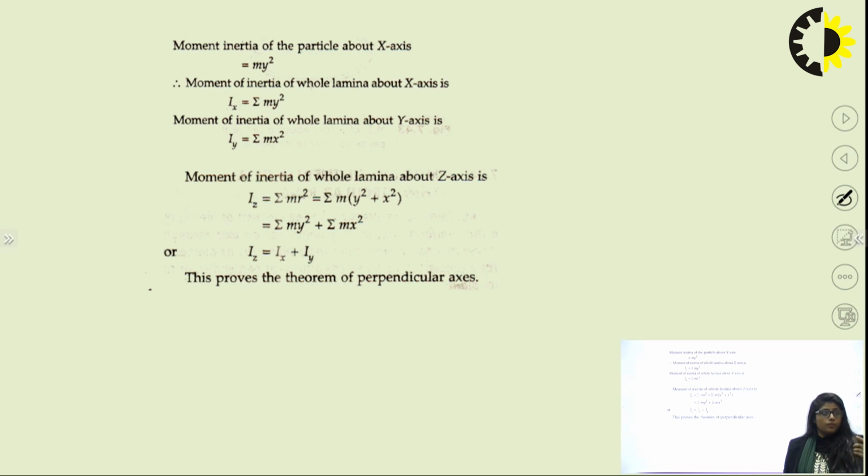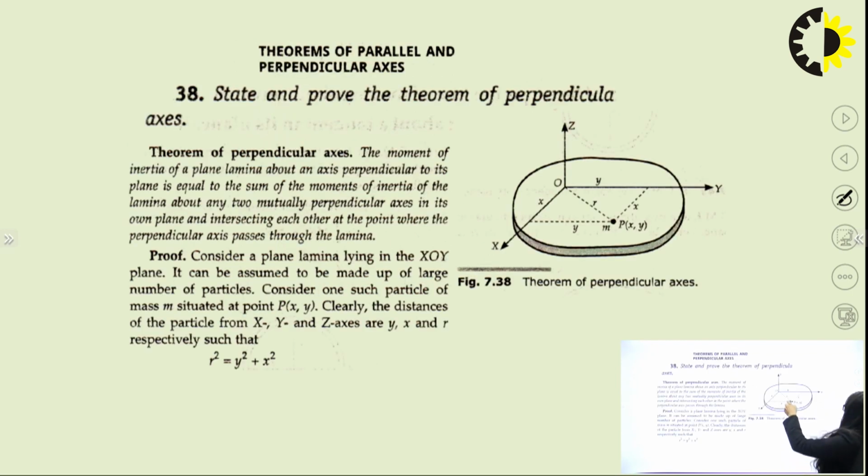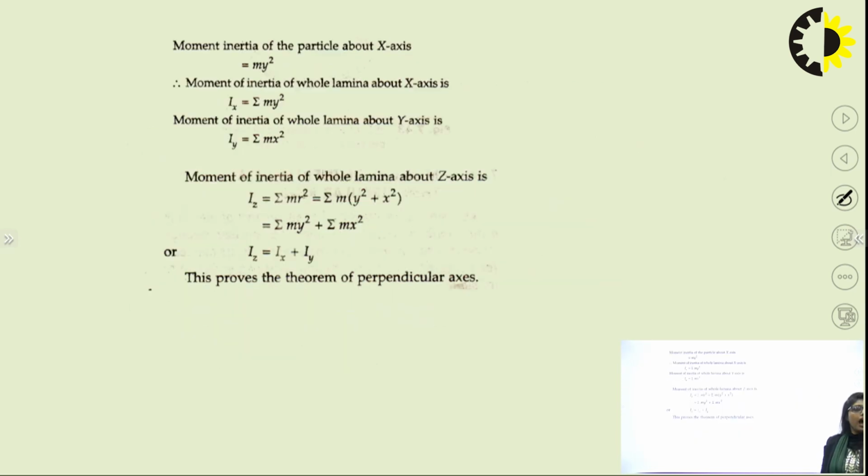If I come to the mass moment of inertia of a particle about the x-axis, listen, if I want to find the moment of inertia about the x-axis, at that time I have to take the distance y. You can see this distance here. If I want to find Ixx, I need to rotate the whole body about xx. So this y is everywhere the radius, right? I can say that Ixx is nothing but summation of m y square.